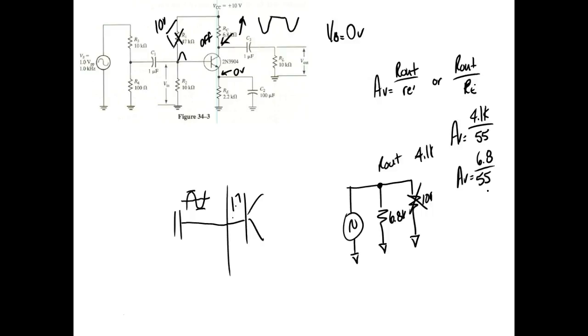But it's not going to do me any good because I don't have an amplifier that runs without a load, right? You understand that? But the load's open. Well, when I'm troubleshooting, I'm expecting a gain of 70 something, and all of a sudden I'm getting a gain of 90 or 100, and I say, well, something's got to be going on. This amplifier is not loaded. So when we load an amplifier, the output goes down, right? If we unload it, the output goes up.